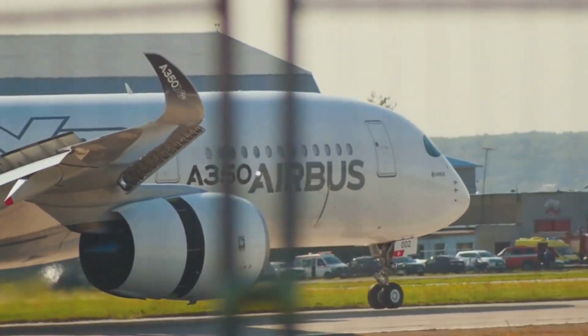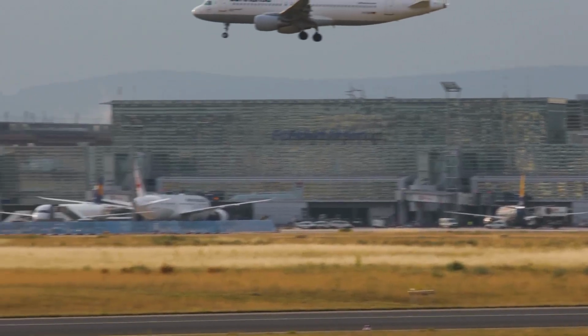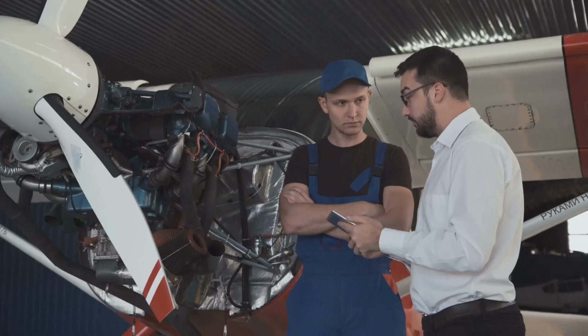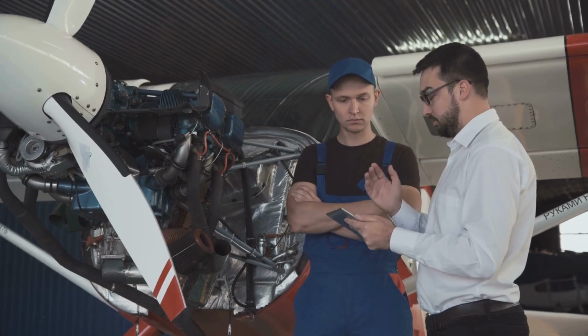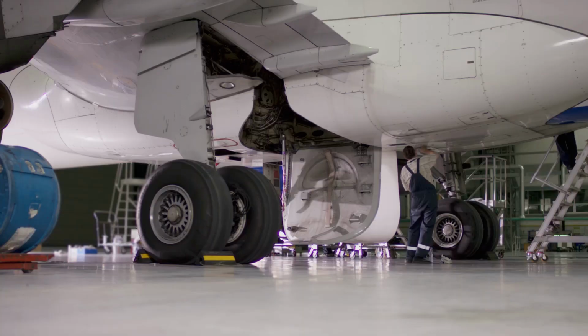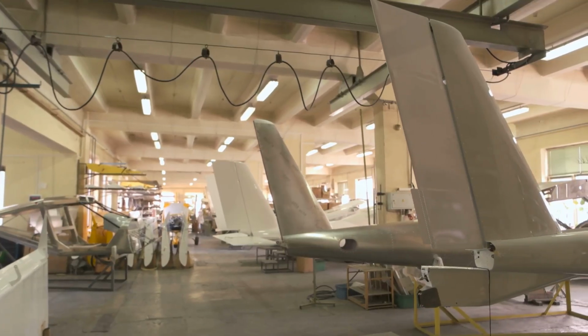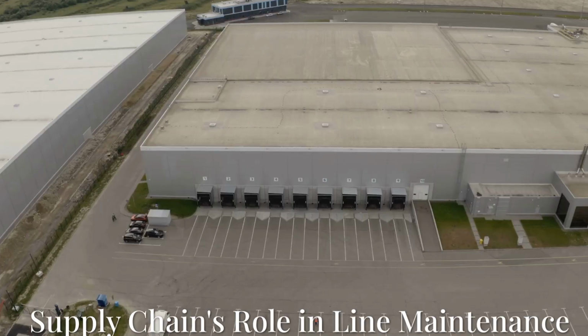Example: a Qatar Airways A350 lands in Frankfurt, and the crew reports a fault in the nose landing light. The local line maintenance team refers to MEL guidance, removes the faulty light, installs a spare from local stock, and clears the fault before the next departure, minimizing downtime.